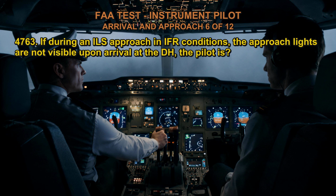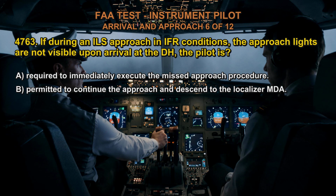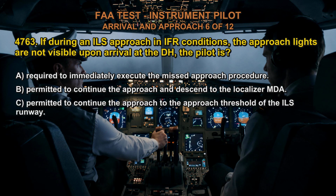4763. If during an ILS approach and IFR conditions, the approach lights are not visible upon arrival at the DH, the pilot is A. Required to immediately execute the missed approach procedure. B. Permitted to continue the approach and descend to the localizer MDA. C. Permitted to continue the approach to the approach threshold of the ILS runway.